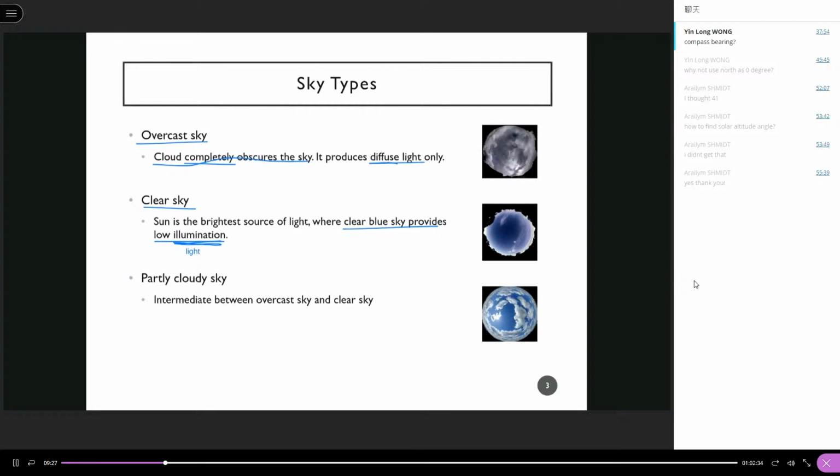But of course you have the sun. The sun is very, very strong. It has a very high intensity. So the adding illumination, or the summation of the illumination due to the sun and due to the blue sky, must be larger than that of the overcast sky. But if you only study the sky component, the blue sky illumination and the overcast sky illumination, usually the overcast sky will be even brighter than the blue sky.